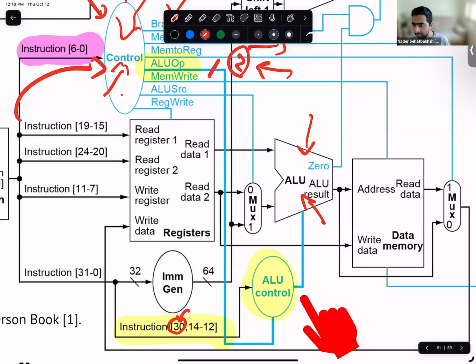Another question is, does checking func7 after func3 have a similar check for a certain pattern if it needs to check both? Well, what happens here is that this is not sequential checking. We're going to feed all of them together and then create a logic here so that as soon as all of these bits are valid, the output would be valid. Okay, this is how we're going to create this.